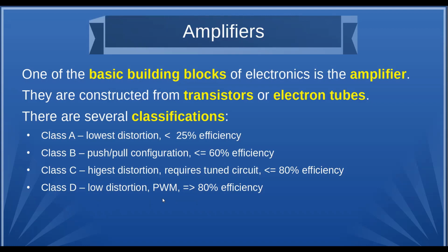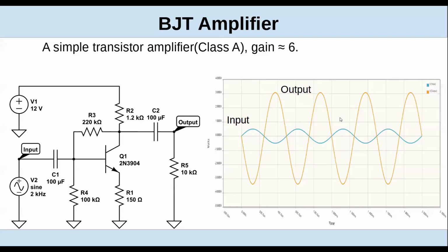And those are easy to amplify digitally, and then you run it through filters to get the audio frequency back. They typically only use these in lower frequency audio work. You know about sticking bandpass filters on the end of it? Low pass filter, okay, low pass. We're not on the filters yet. We'll talk about them.